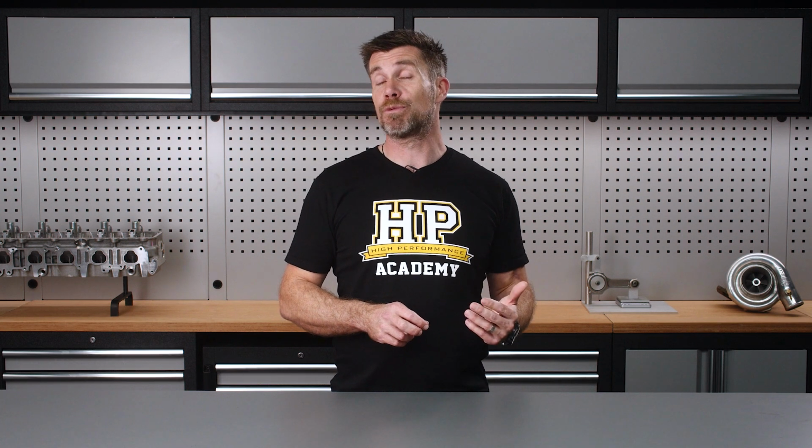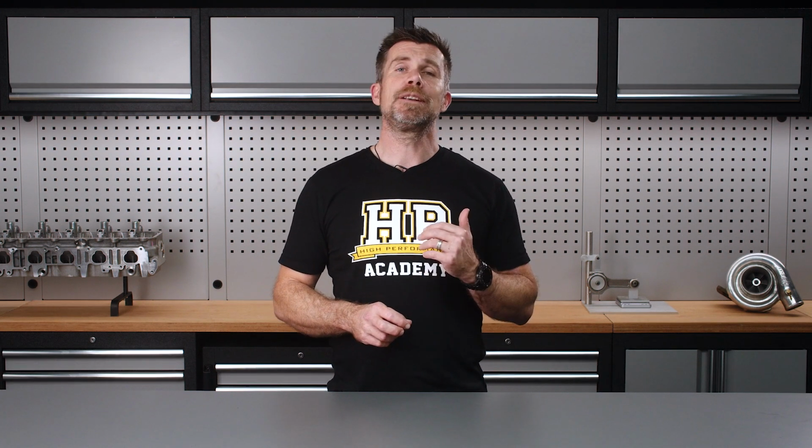There are many factors that determine the amount of time between when the spark occurs and when peak cylinder pressure is reached, and we'll discuss these now. First up, we have the diameter of the cylinder. It takes a certain amount of time for the flame front to travel across the cylinder, so the larger the cylinder diameter, the more ignition advance we'll need. Smaller cylinders, on the other hand, require less ignition advance.